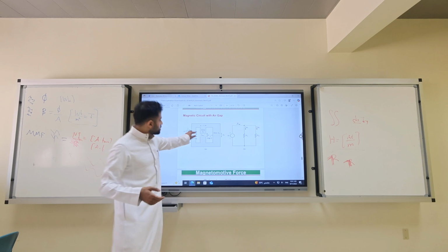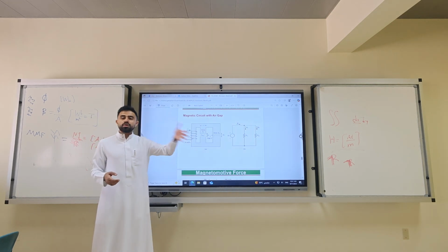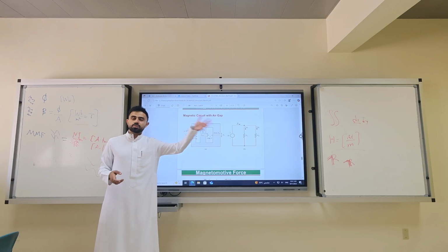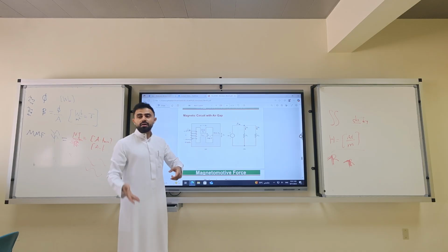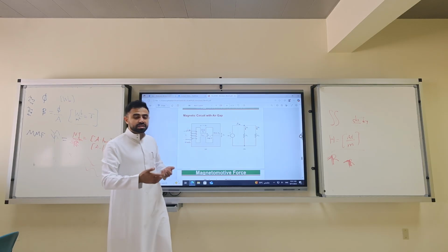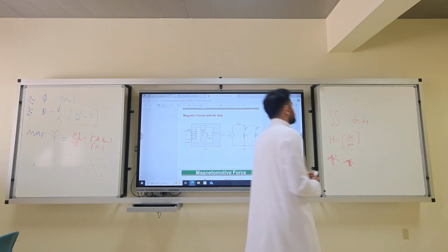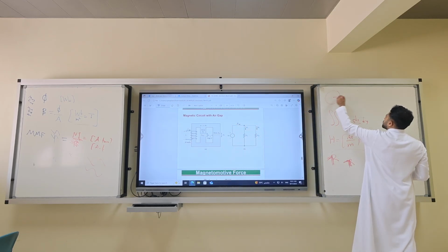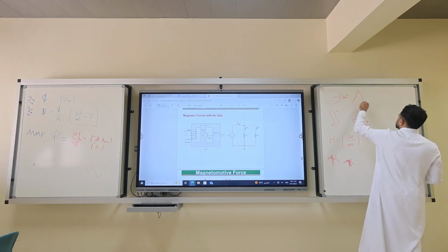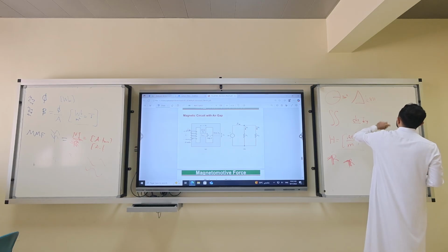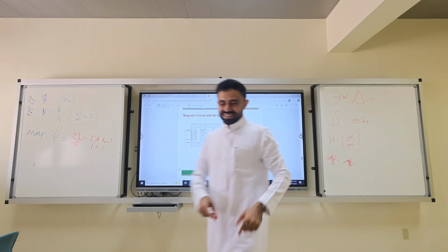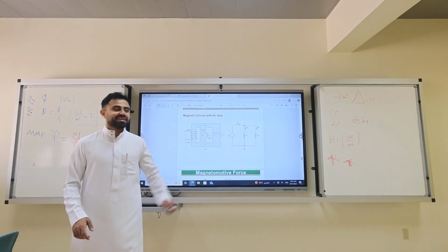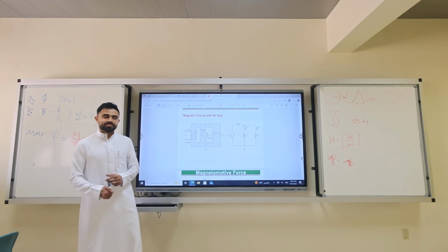Air gap. You have to measure it, and again you apply the formula. L over mu. What is mu? Mu naught, because mu r is 1 in the air. Times the cross-sectional area. Cross-sectional area of a triangle, of a circle. Trick in the exam. What is the area of the circle? Pi r squared. What is the area of a triangle? Half the base times the height. What is the area of a parallelogram? You don't know. Figure it out. It's base times height.